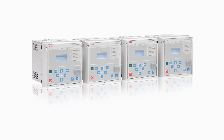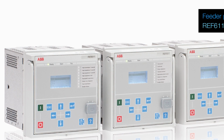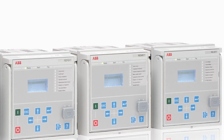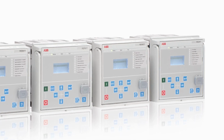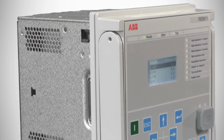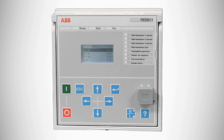There are 4 relay types: the REB 611 for bus bar protection, the REF 611 for feeder protection, the REM 611 for motor protection, and the REU 611 for voltage protection. These protection relays are pre-configured for fast setup and commissioning. Once you have entered the application-specific parameters using the web HMI, the relay is ready to be put into service.